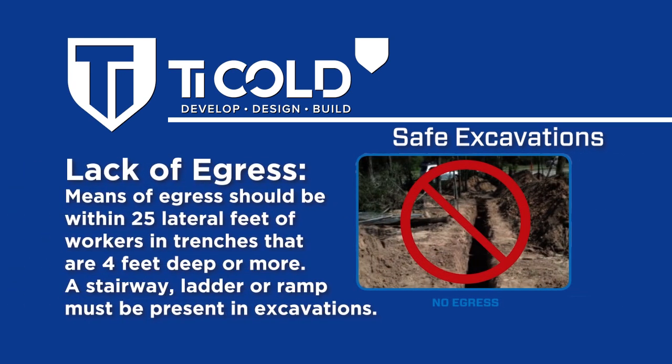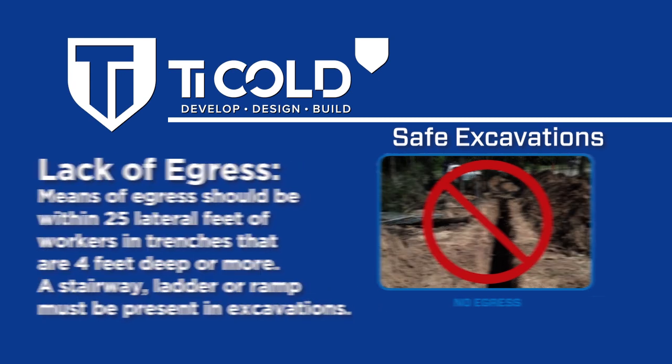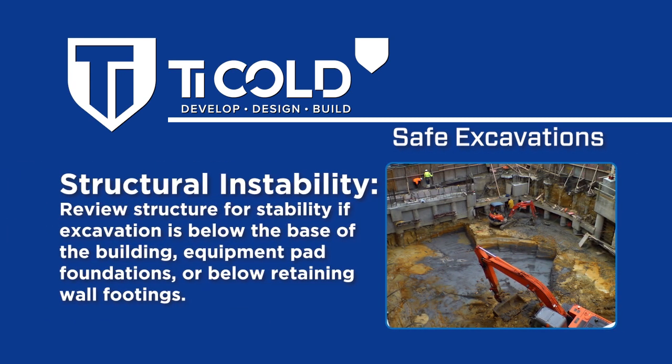Lack of egress. Means of egress should be within 25 lateral feet of workers in trenches that are 4 feet deep or more. A stairway, ladder, or ramp must be present in excavations. Structural instability. Review the structure for stability if excavation is below the base of the building, equipment pad foundations, or below retaining wall footings.